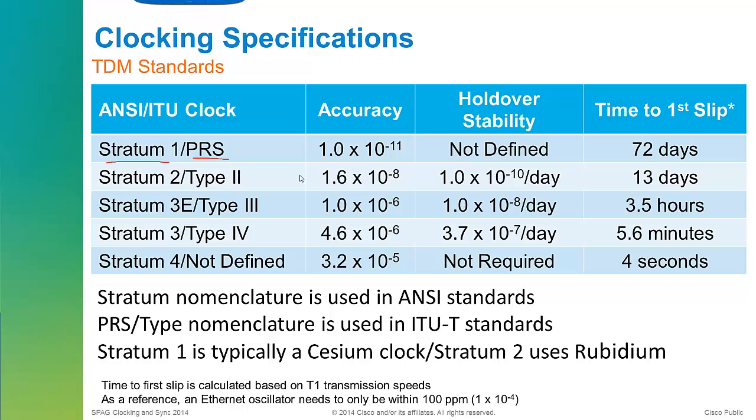They also sometimes change speed when they're new. So in the first 30 days they might vary a little bit in speed. These oscillators, and it's the same for all oscillators, these are all merchant silicon, and then they'll settle down and they'll work fairly well for a number of years. And as they get older, they might start changing again.